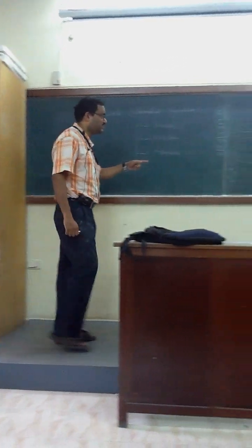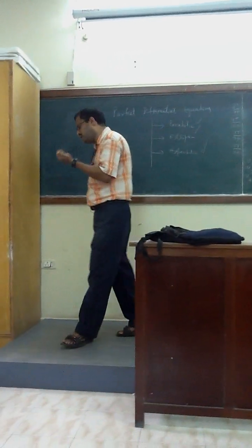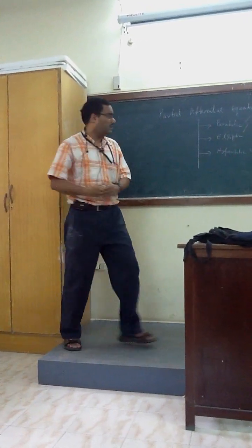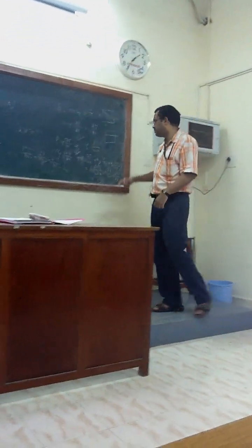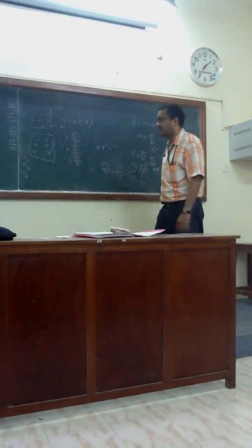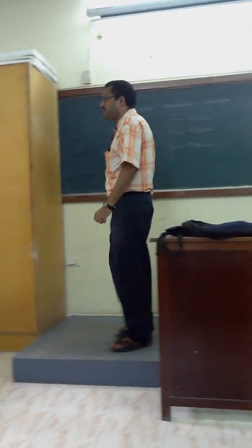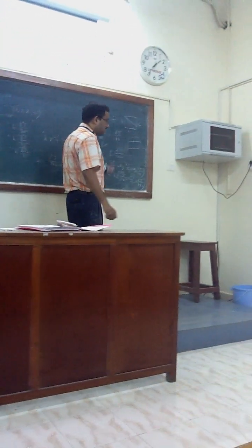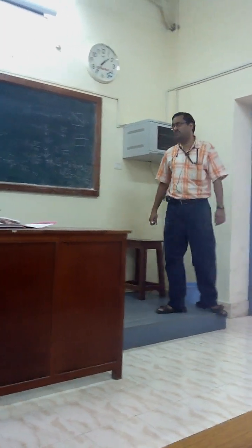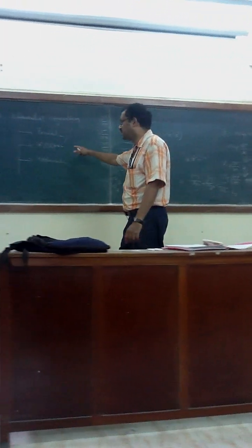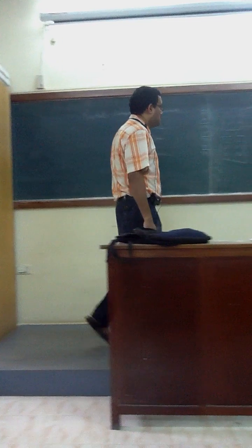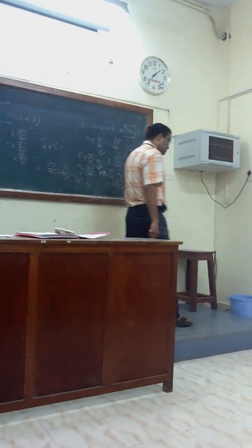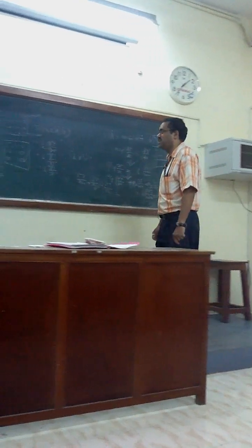But you see that time is missing: the steady state. I have switched off the Bunsen burner, enough time has elapsed, but still some portion is hot, some portion is cold. Because of the thermal conductivity, we have some resistance, and based on that, temperature is a function of x, y, z. This type of equation is an equilibrium problem, which does not evolve with time. But the system has resistance, things vary from position to position. This type of problem is termed an elliptic problem. So elliptic means the system is at equilibrium, but it has position dependency, and it does not have time dependency.